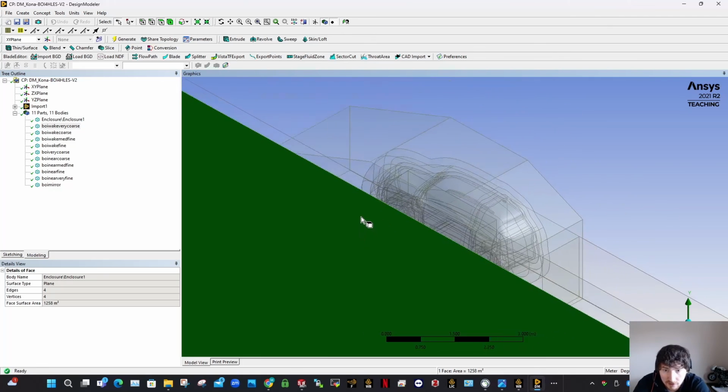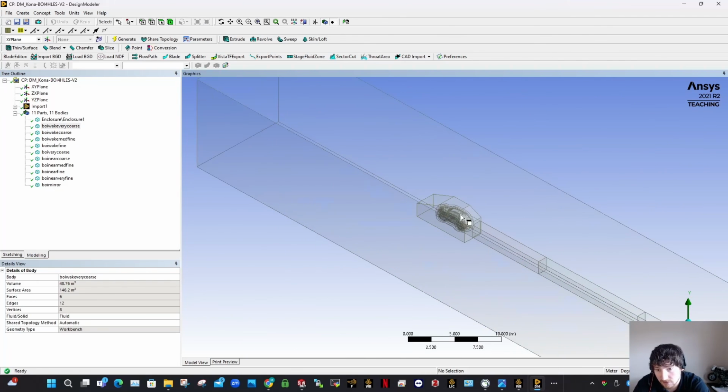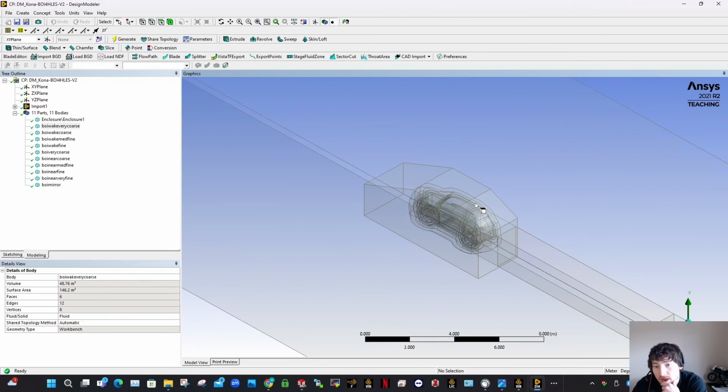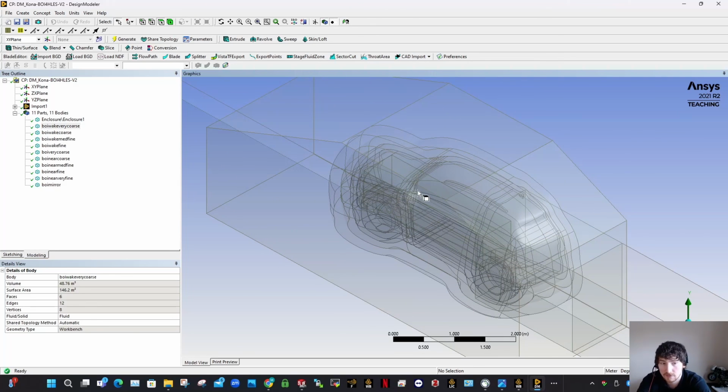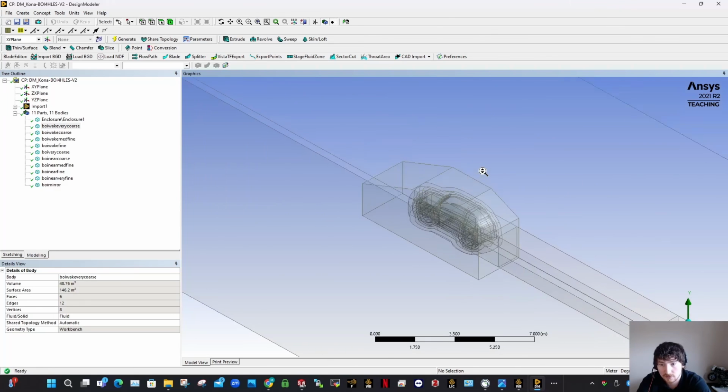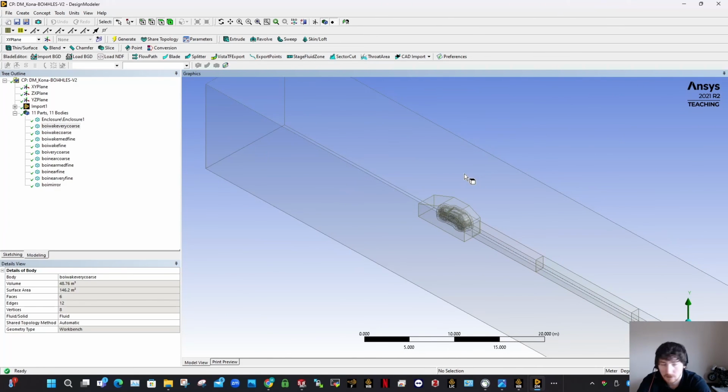And then the boundary layer, that's grand, so that should mesh everything for you. And then the boundary layer that I grow on my vehicle here, I keep all my bulk face elements for the hybrid LES at 5 millimeters. And then I'll add the video where I push this through, and I do like a 16 layer boundary layer on this, but it'll be on a different vehicle, and some of the BOIs mightn't be here. But remember the sizing's there, and you should be good to work with that. Okay, thanks.